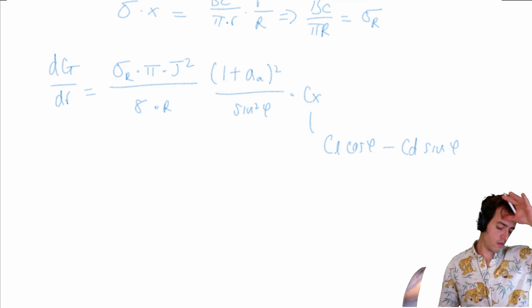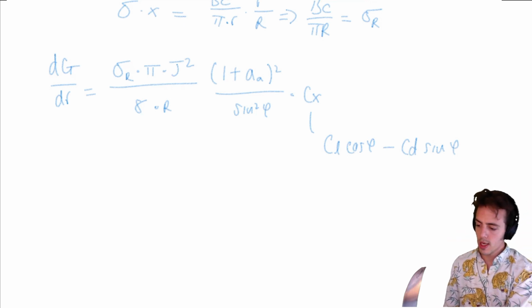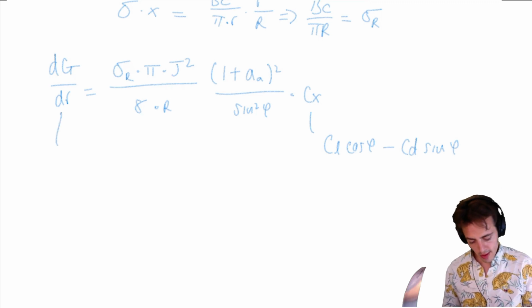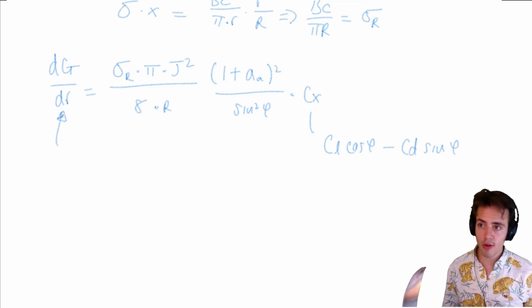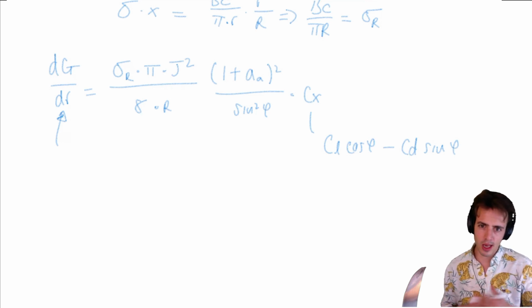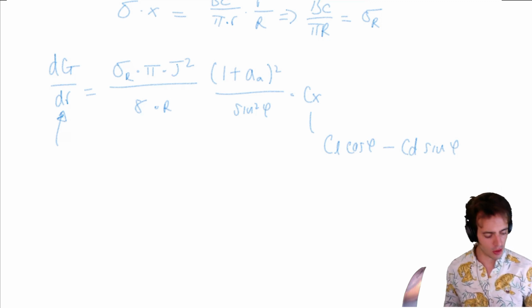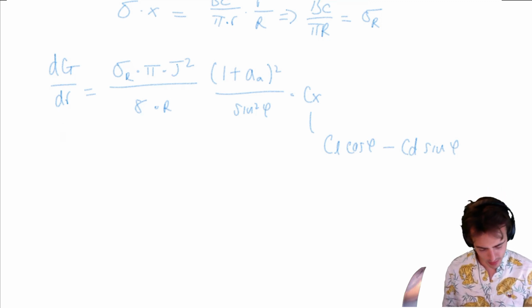So we've got an expression for our thrust gradient now. This is still in terms of a dimensional thrust gradient because we've got a dimensional numerator. It would be useful if we could then just have this over dct on dx, which is then this non-dimensional span-wise ordinate.